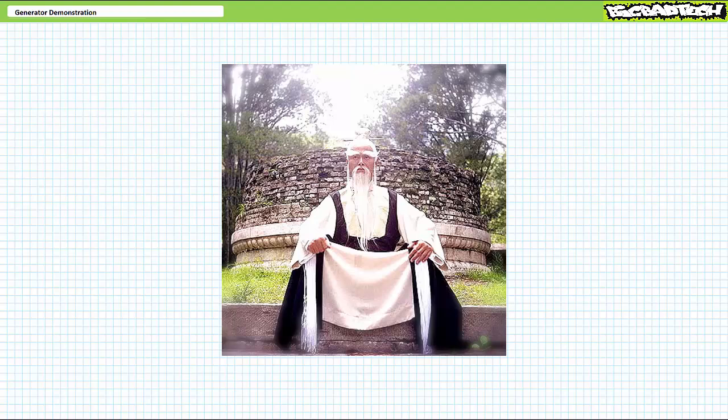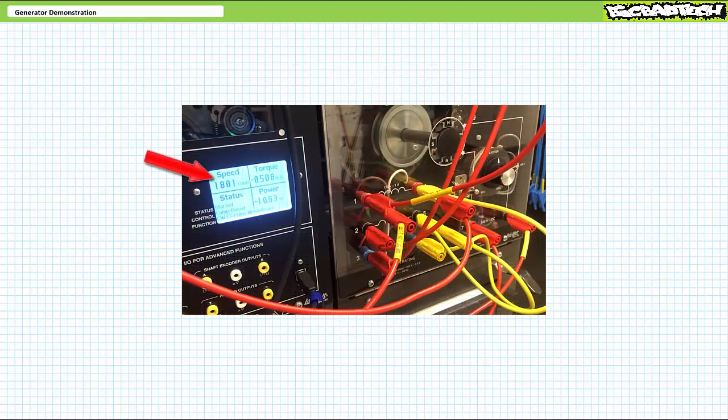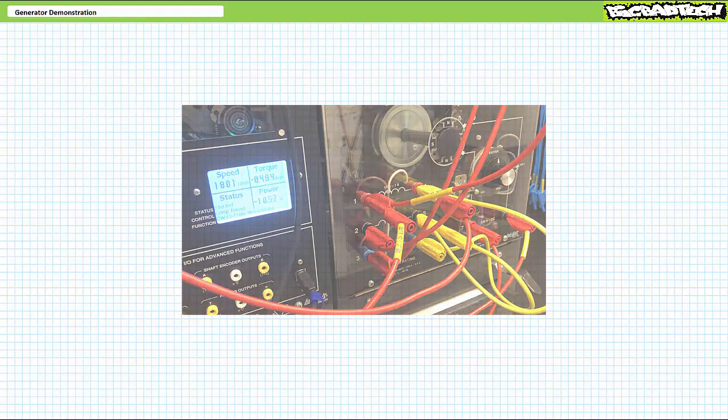Even though the prime mover in part 1 was using closed-loop speed control, it wasn't as sophisticated as I made it sound. Every time the electrical load demanded more real power, the prime mover experienced an increase in counter torque and briefly slowed down. The closed-loop speed control system recognized this fact and increased mechanical power until speed stabilized at the desired 1800 RPM. Similarly, every time the electrical load demanded less real power, the prime mover experienced a decrease in counter torque and briefly sped up. The closed-loop speed control system again recognized this fact and decreased mechanical power until speed stabilized at the desired 1800 RPM.